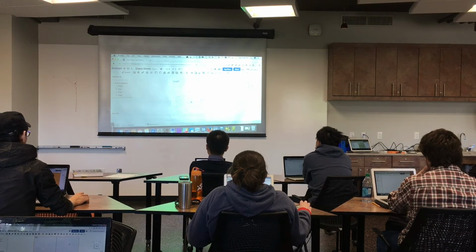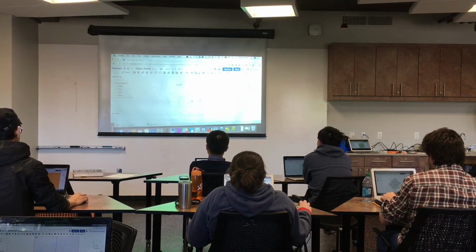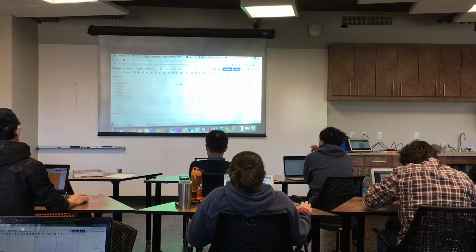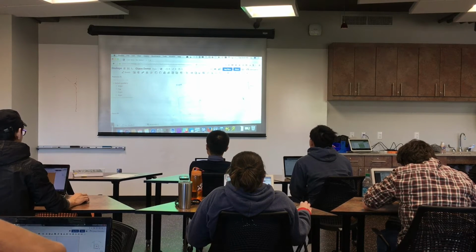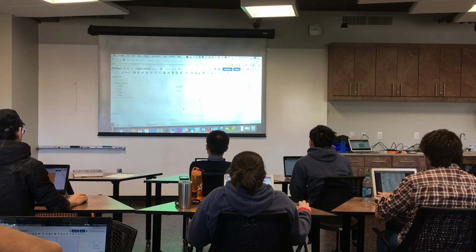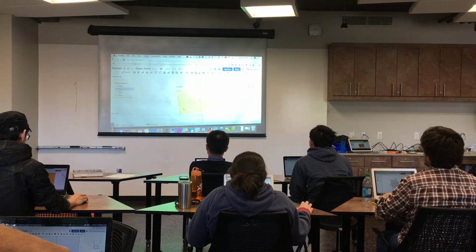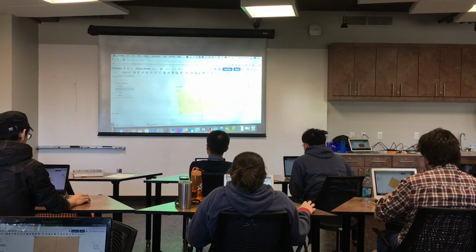All right. The whole idea of making parts in this kind of a CAD environment is by sketches, and then we extrude or we make a pocket from the sketch, or we pattern something on the sketch. And a sketch is just a 2D entity. So for our part, click the top plane, so that the top plane is highlighted like this, and then come up here and click Sketch.